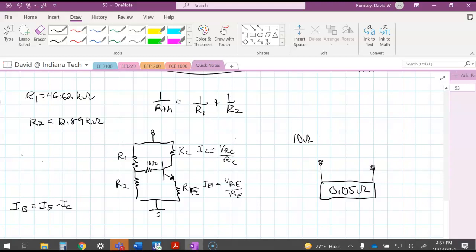And the chip is measuring the voltage across that resistor to actually measure the current. Those resistors typically have to be 0.1% or even better, because the computation done inside the chip assumes that it's 0.05 ohms.